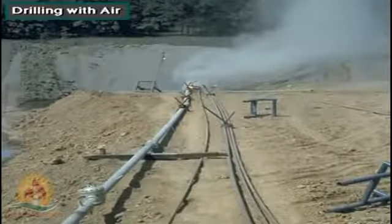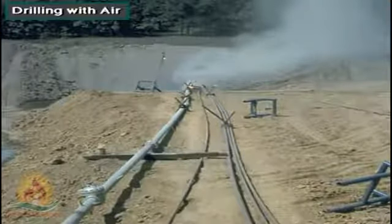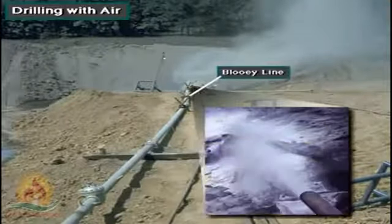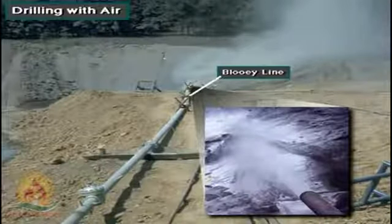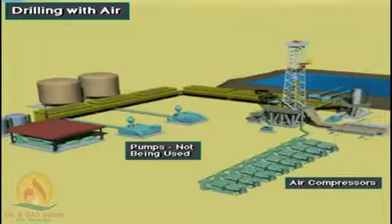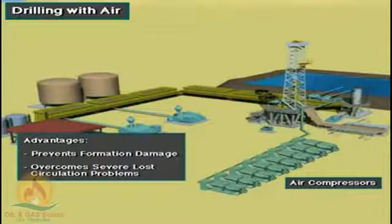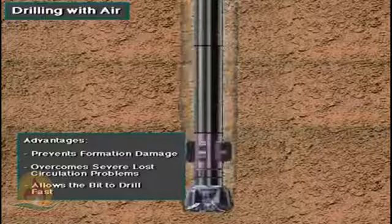Sometimes drilling fluid is dry air or natural gas. Here, dry air is coming out of the rig's blooey line, carrying very fine drilled cuttings. Air drilling uses large air compressors instead of mud pumps. Drilling with air or gas can prevent formation damage and can overcome severe lost circulation problems. And it allows the bit to drill very fast.